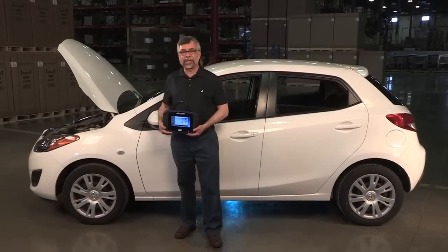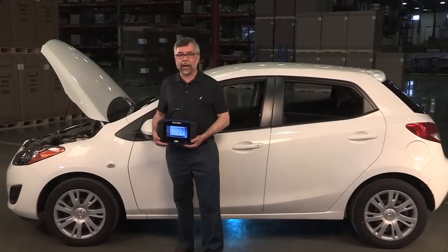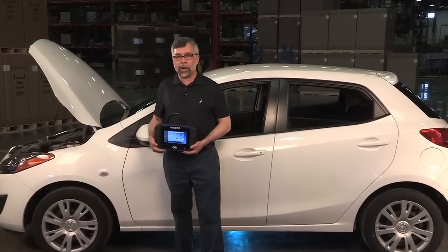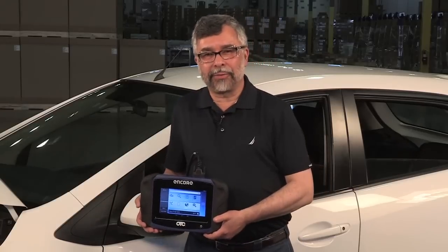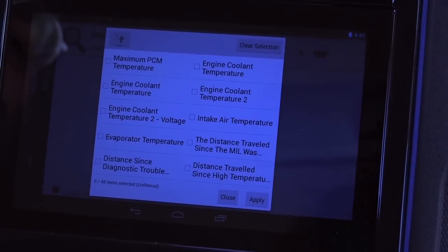I'm going to show you how to diagnose drivability issues quickly to determine whether the vehicle has an air, fuel, mechanical engine, or exhaust issue. Volumetric efficiency testing is the verification of an engine's performance calculated for the amount of air used. Performing a VE test can reveal the accuracy of the vehicle's mass airflow sensor, but more importantly, it can quickly diagnose drivability issues. There are a few things you will need to do before performing a volumetric efficiency test.